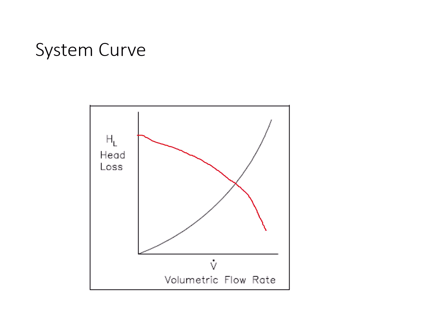Okay. I hope, if for that pump the efficiency curve is like this, I think this will give you a very low efficiency, and it is not a good selection of this pump. You should select a pump that has an efficiency curve like this, so that the maximum efficiency satisfies your design flow rate.